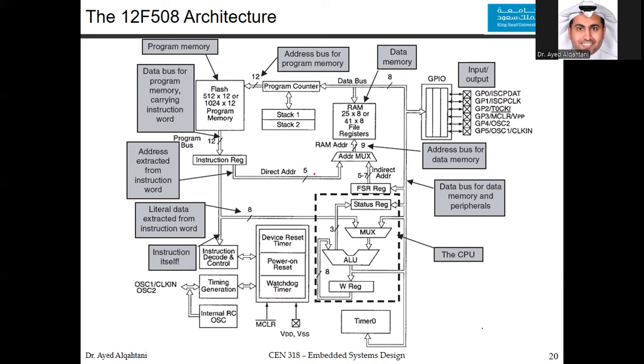and you can supply it to the memory where you can access part of it for what we call the offset or the immediate values of the instructions. You get it here with another value, probably a base register, to access the file register or the memory, and based on this, you get the data out or store the data in.